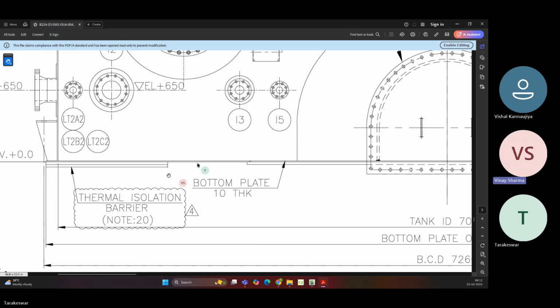This base plate is there, and below that base plate one big foundation is there, according to the weight of the cylinder. That will be a concrete foundation, and its size is around, for example, if your cylinder is 6 meters, at least one third of that should be there. That's the standard formula: one third of the equipment, plus its nozzles and all weight.